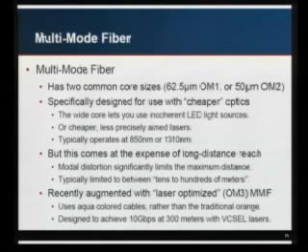expense of distance. Because it's so wide, it's basically the light version of multipath interference from radio. You have multiple ways the light can travel, and so you end up with all these extra echoes and things like that, and it's called modal distortion. And it basically limits you, depending on the bandwidth and the type of fiber that you're using, to somewhere between tens to hundreds of meters. You could get longer with really low speed optics, but it's limiting.